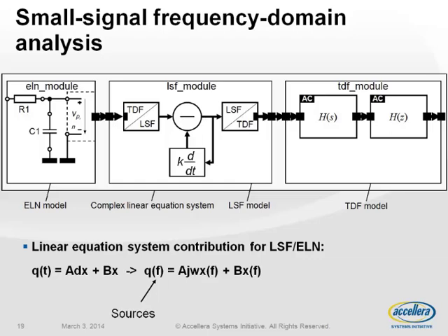The cluster of interconnected ELN primitives will provide an equation system for the cluster from the input to the output, so that this behavior can be accounted for. The same will hold for the LSF module. And for the TDF modules, you will have to provide the transfer functions for each of the modules. And we will see it now in a small example how you can do this.